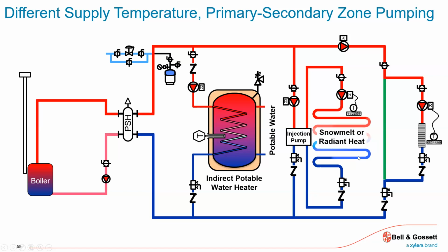So unless that pump turned on and created its own set of pressure differential, and now he's saying, hey, I want some flow through here. I'm coming back to this T, plus I add up this. So now I'm injecting more GPM, perhaps more hot water, cool water is moving back here, which means more hot boiler water is moving out here.